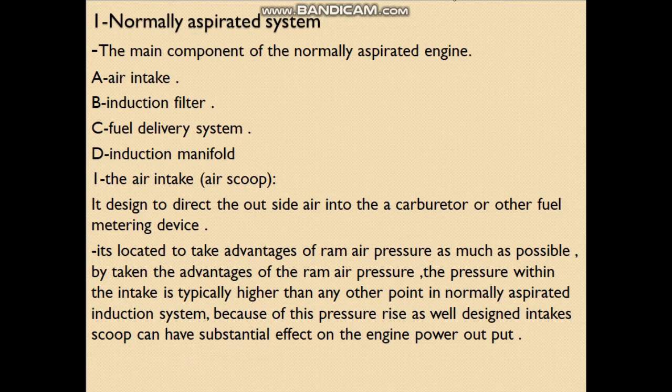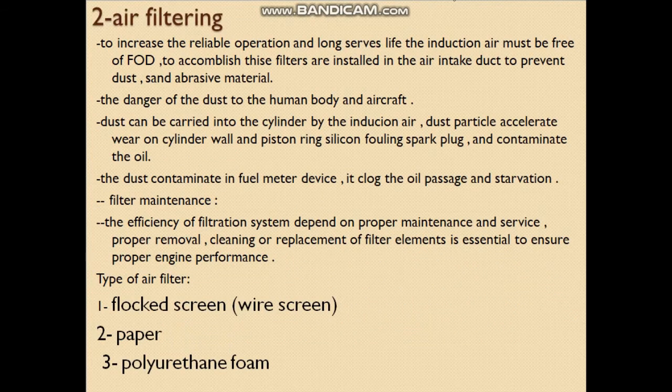The second component is the induction filter. Air filtering is used to increase the reliable operation and long service life of the engine. To do so, the induction air must be free of FOD, foreign object damage.